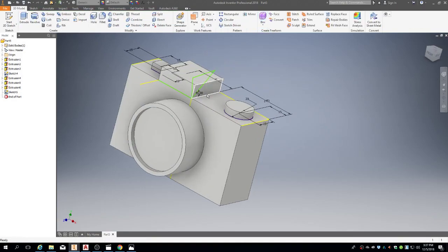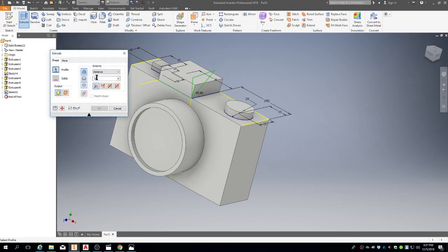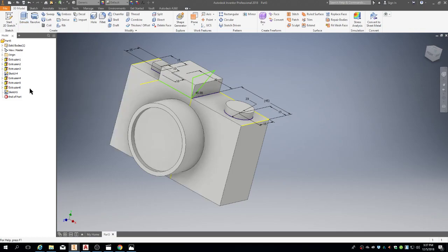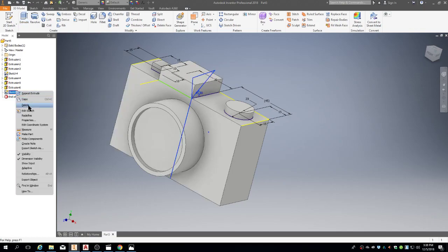Finish that sketch, and then use that shape that you drew to negative cut across the object. I'm going to cut all the way across the object like that. I don't want to do it. That's too many steps. So what I'm going to do is go back, delete that sketch, and do it an easier way.